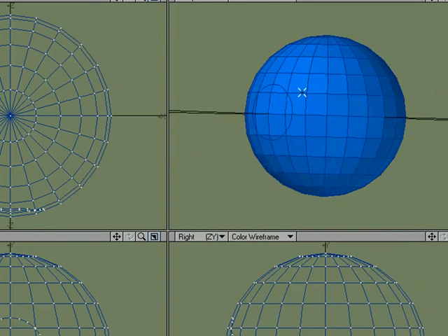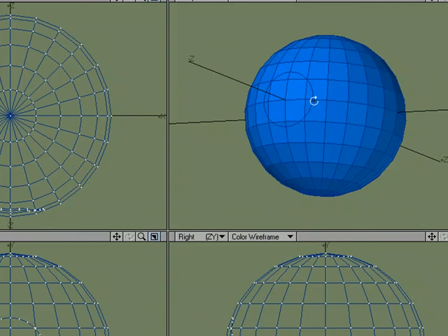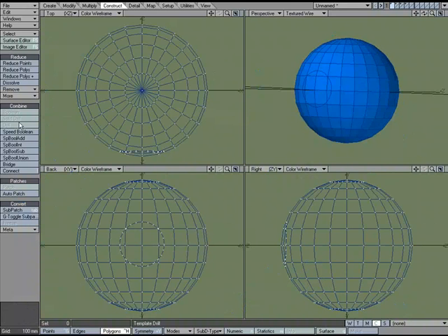Okay, so that's a quick look at using drill and solid drill. Both are drill tools. Remember that drill works with flat shapes as your cutter, and solid drill works with three-dimensional shapes as your cutter. And they both perform the same operations. The only other thing, just as another reminder, is that if you use drill, make sure you pick the right axis or you might not see anything happen, which is usually the case if you pick the wrong axis, or you might just get undesirable results. So pick the right axis with drill and make sure you have a three-dimensional object with solid drill and you'll be set.